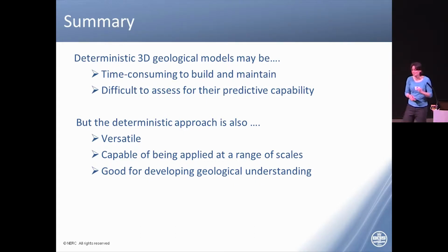We can also, and this is a new development in the software, include scattered data points. Where you've got an awful lot of data for a certain thickness, you export it as a text document, bring it back in and use it in the control of sections. So when you do the interpolation step from cross section to surface, you can include those data points as things it will interpolate to when it creates the surface. So that's relatively new.